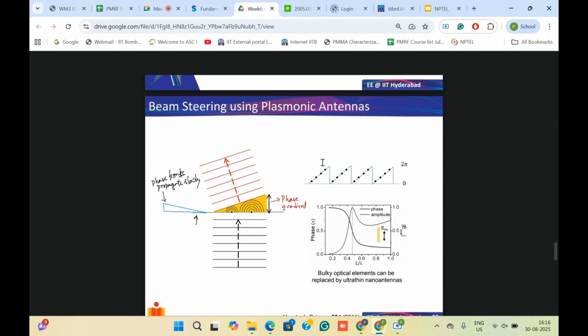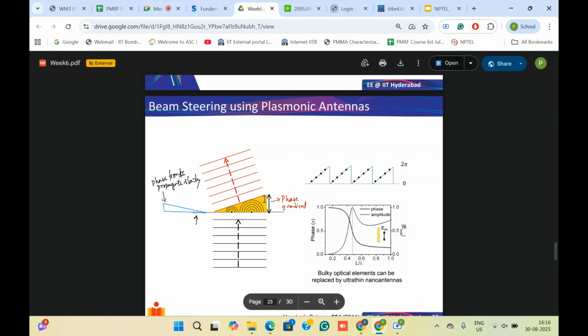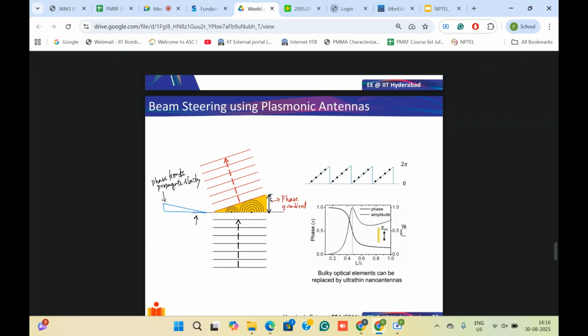So, for example, this beam will introduce a secondary wavefront here, and that will start propagating its wavefront like this, and another point will again contribute another secondary. Okay. So all of these wavefronts will propagate, and eventually there will be an overlap, and the overlap of the phase fronts is what defines the direction of the beam, and that's how a beam propagates at an angle.